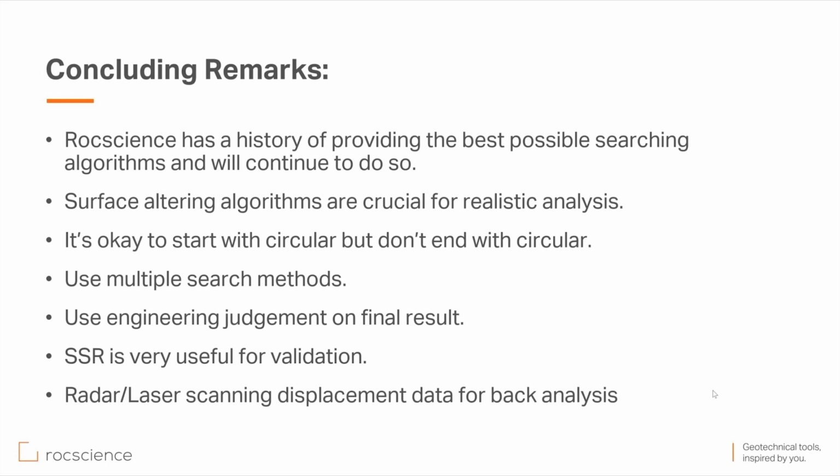And that leads into my next comment, which is to always use your engineering judgment. You should look and see, is what my program, and it's not just Slide, it's any other commercial product out there, giving a surface that is reasonable and what you might anticipate? Look at the normal stresses on the base of the surface. Do they make sense? Is there a lot of tension on the base? And tension, as we know, has a very adverse effect, especially in materials that can't take tension, like a lot of soils and a lot of rocks.